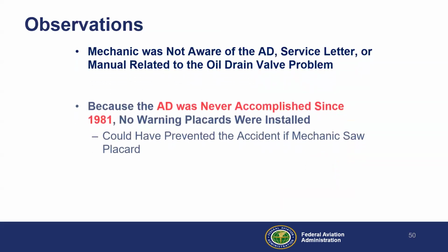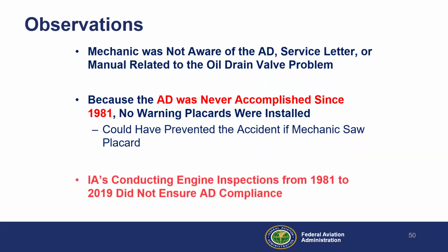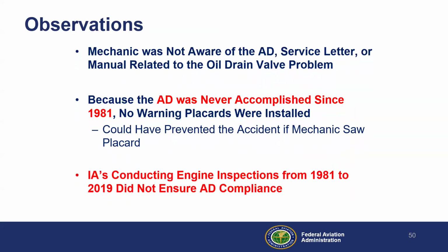So the mechanic was not aware of that AD, the service letter, or the manual. And this AD of putting those placards on was never accomplished since 1981. This may have prevented that accident. So IA conducting engine inspections from 1981 to 2019 did not ensure AD compliance.